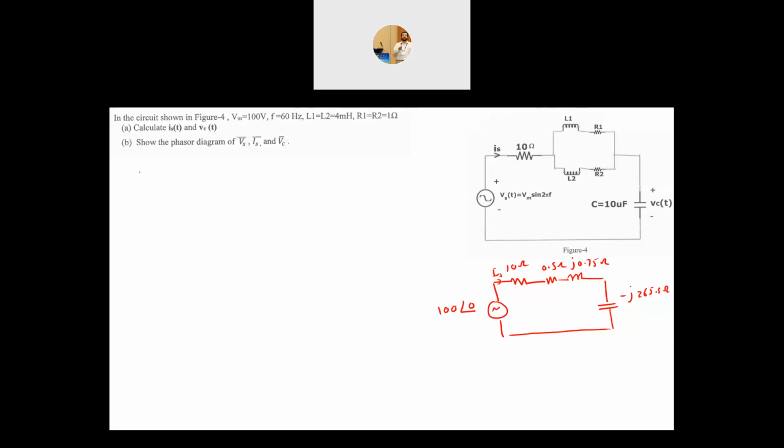Okay, your IS, this is Ohm's law. Now here is the beauty of the frequency domain. You apply everything you have learned about the circuit. The only difference, as I mentioned, is that you are not dealing with scalars, you are dealing with vectors. So this is IS, the current here is basically the voltage divided by the summation of all reactances, which we call the total impedance.